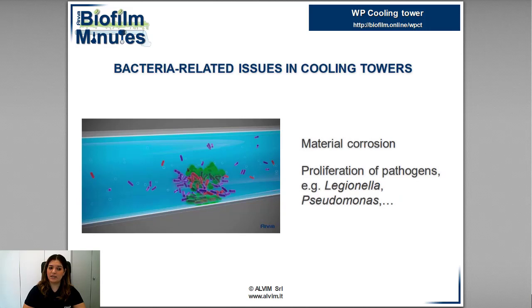The formation of biofilm causes many threats to the cooling towers. First of all, its ability to act as a reservoir of pathogens. The most common pathogens, such as Legionella or Pseudomonas, can persist and multiply in this environment. Due to water flow, chemical treatment or other factors, these microorganisms contaminate the water and can easily spread with aerosol and travel even for kilometers.